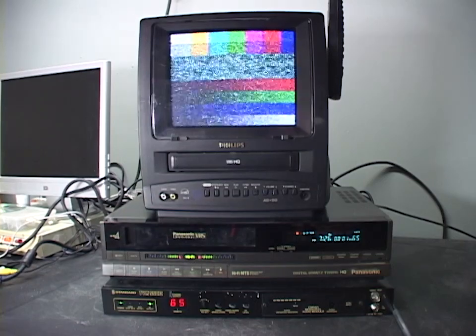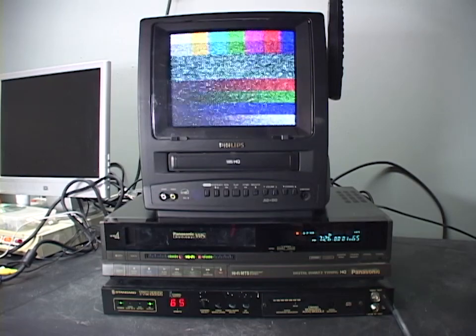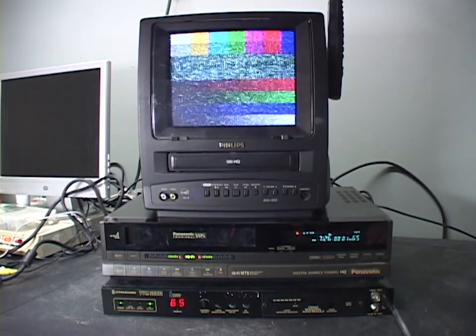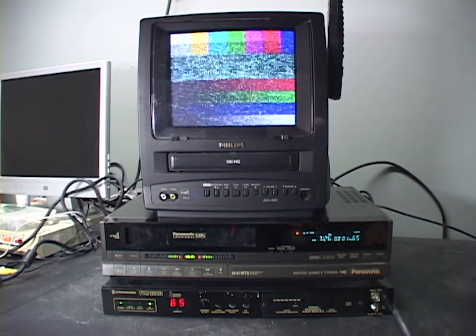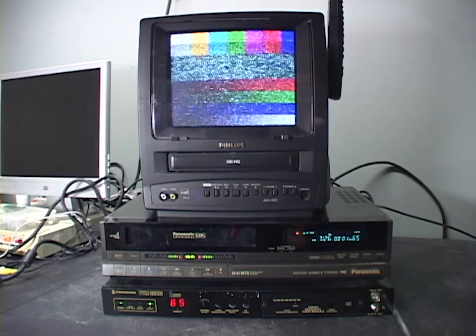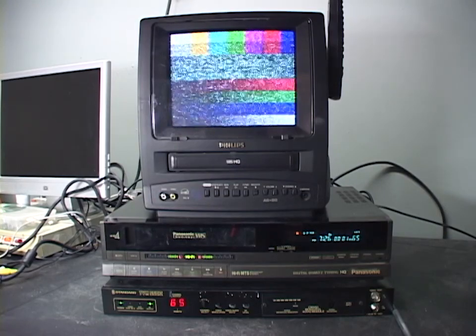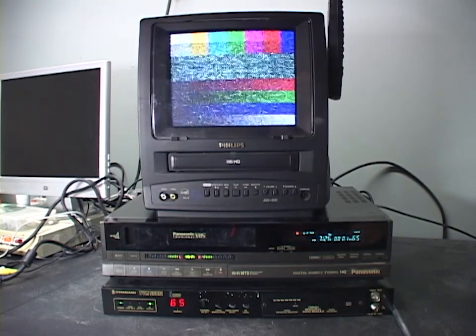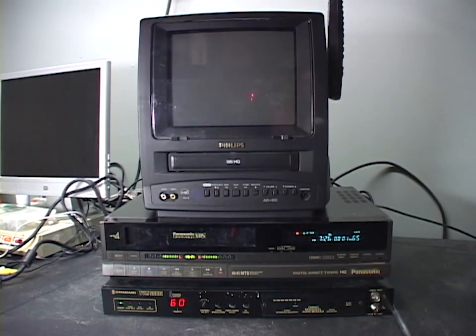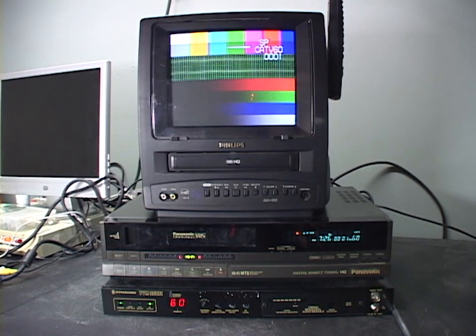The signal is super weak. And I can crank the RF level up, and the picture clears up, but it still doesn't look quite right, so I don't know if there was some standard from channel 65 and above that's different between the VCR and the modulator, or if this VCR's cable tuner just doesn't do very well on 65 and above.